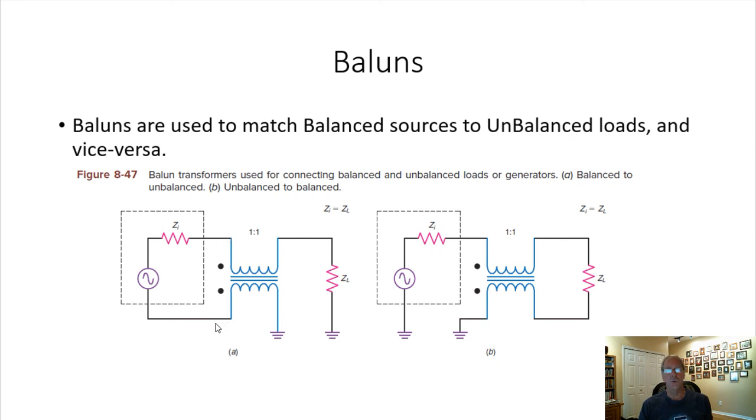The balanced source has two outputs, right? It doesn't really have a ground, right? Both sides are moving. That defines a balanced output. You have a plus and a minus, right? Unbalanced has a signal hot, if you will, and ground. An example of an unbalanced interface would be your cable TV cable or one of the RCA jacks on your stereo. It has an outside shield and an inner conductor. So this would be the outside shield, and that's the inner conductor, right?